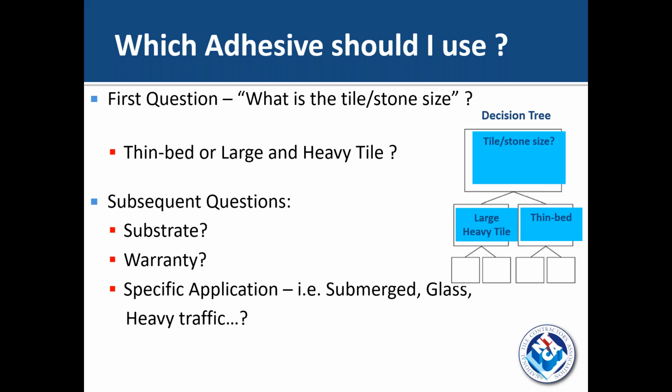Some manufacturers do have ideas of how long they want it to set before people walk on it for thin gauge porcelain tile. So I would just check all your options, make sure you're covering your bases. Yeah, we typically say 72 hours for heavy, but